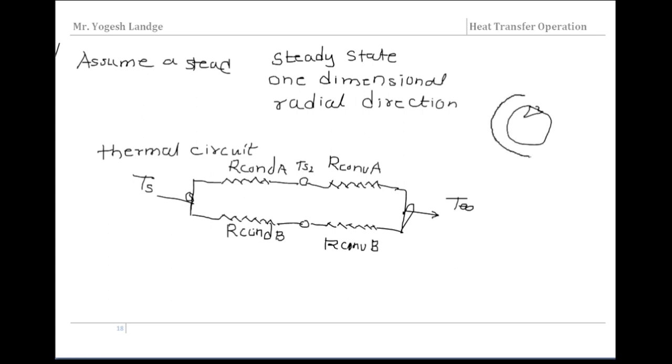And if you see, the first part is this one, so at this one, okay. So this is the thing here. If I want to connect, I can connect like this, okay. And the convection on the surface, and similarly for the next part for B. So once we draw the diagram, we will see that there are four resistances here, and these two resistances, this one and this one, are in series, and then it is parallel.